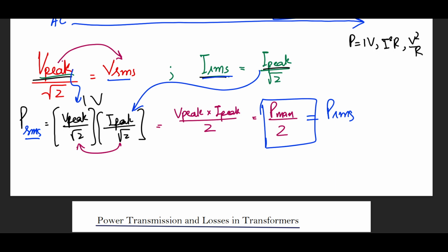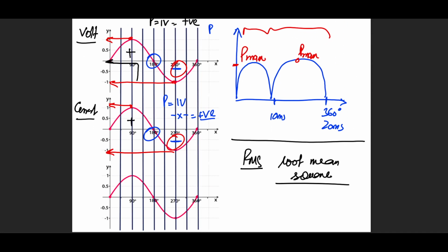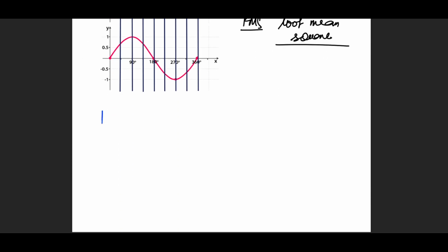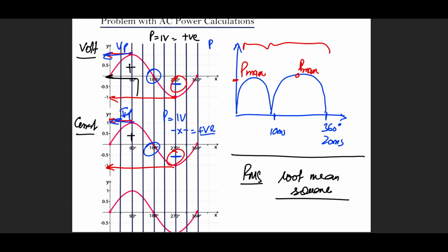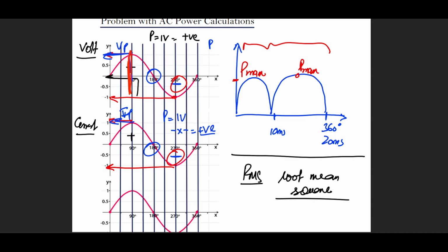What does this mean? It means that if I had the peak value of current and voltage, I peak, what I can do is find the maximum power by multiplying this I peak multiplied by V peak, or maximum value, right? This will give me the maximum power delivered, but at a single instant. Notice that this is only happening at one instant in time. This is not happening continuously. This is actually just one time when the current and voltage have the highest value.